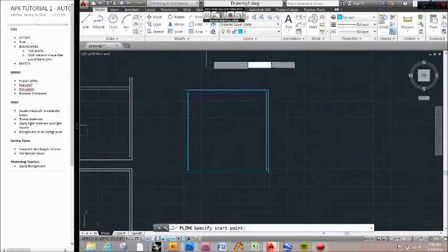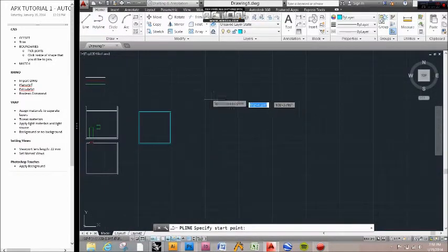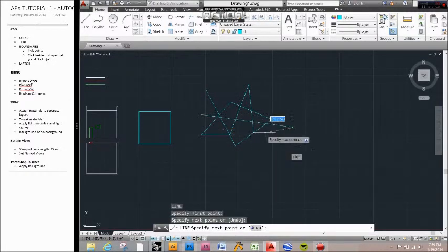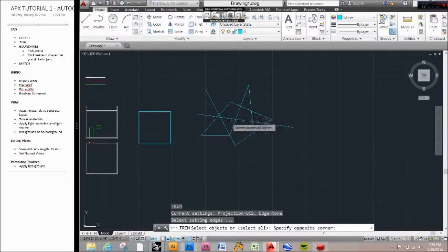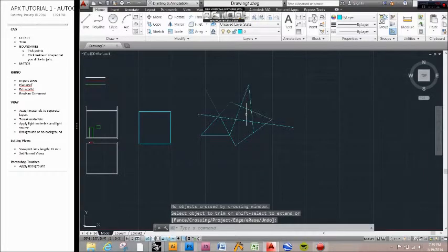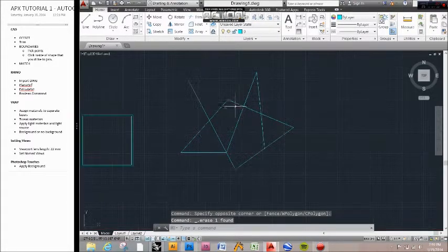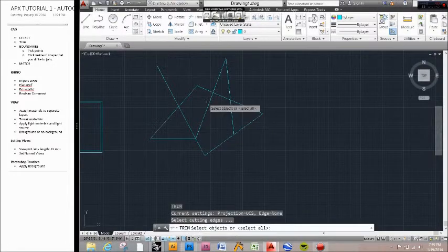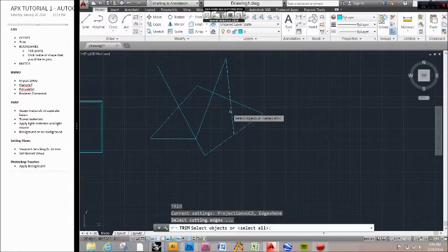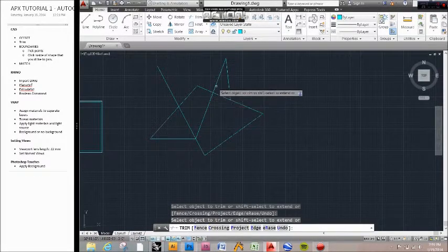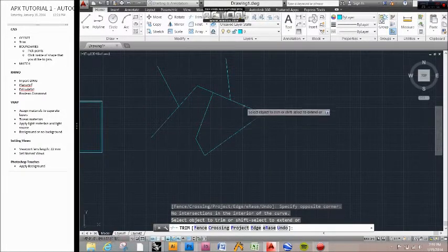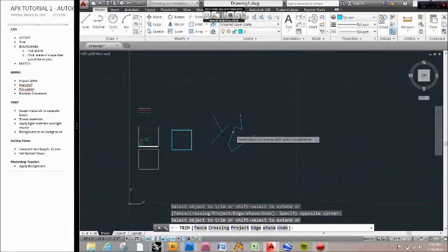Now, for trimming, the reason why I go with trim is because for a long time I thought that trim was just exclusive for hitting the source and then trimming, but the trim tool is far more versatile. You can write TR, hit enter one more time, and you can trim whatever you want. It doesn't have to specify the trim source. This will save a lot of time.